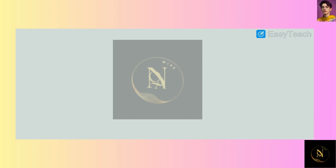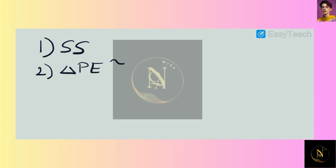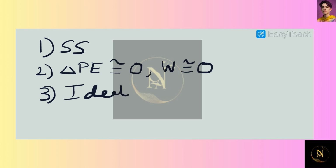So the first thing we're going to do is write down our assumptions. We're going to assume that this is a steady state process, so nothing is going to be changing with time. We're also going to say that changes in potential energy are negligible, as is anything related to work. And we're going to assume that we're dealing with an ideal gas with constant specific heats.